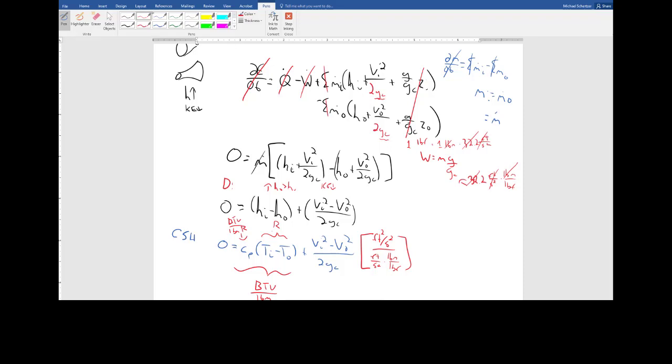Now, what do we do with these units? For feet per second squared, I get rid of one of these feet and get rid of the second squared. Now what I have is equal to foot-pounds force per pound mass. That's okay, because at least it's the right quantity. It's energy, foot-pounds, force times distance, over pound mass, and this is also energy per unit mass. It's just not the right kind of energy yet.